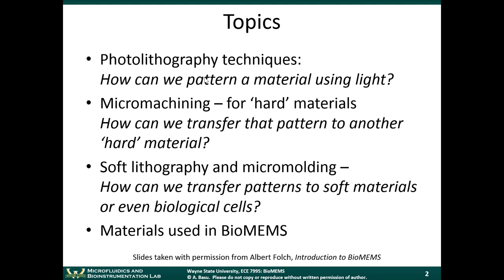You can use two-dimensional techniques, you can use mask-based techniques, you can use maskless techniques. There's a thing called the Rayleigh diffraction limit, which limits the smallest size that you can make. So with optical techniques, you can get things down to 10 to 50 nanometers. But with electron beams, if you focus them well, you can get down to much smaller than that. There's something called focused ion beam that I haven't talked about, where you use a stream of gallium ions. That can get down to even smaller sizes. But the ideas are the same.